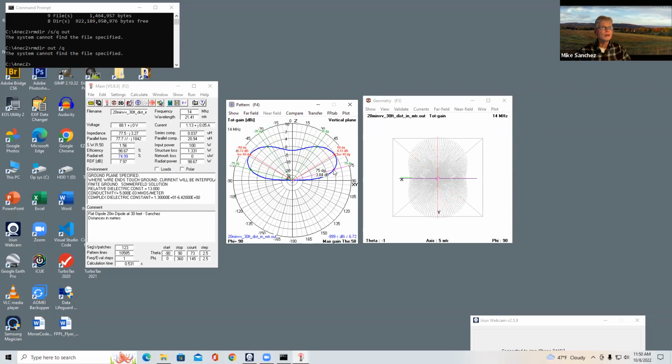I did some work with comparisons between the hex beam and this spider beam, and this was extraordinarily useful because we're trying to do field day with it, so we have to cover a wide angle. And it wasn't so much the max gain we were hunting, it was more the broadband nature in terms of the angle, so we could cover the whole United States without having to manually move the thing during field day.